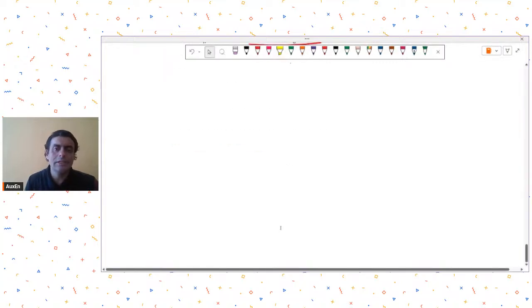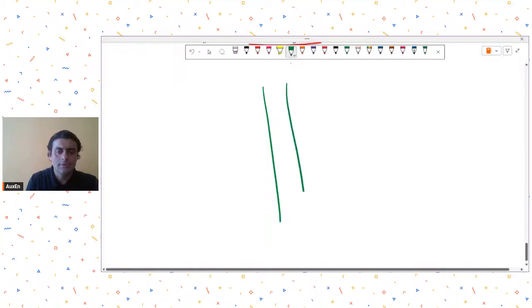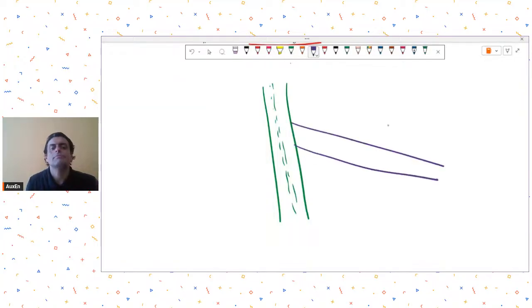I think what he is asking is that in plan view, if I have a beam like this, this is the plan view, and this is the web, let's say, and another beam is connected at some angle, how should the connection be done? Let's say I'm only talking about the shear connection right now. For shear connection, you can go for a fin plate connection in such cases.